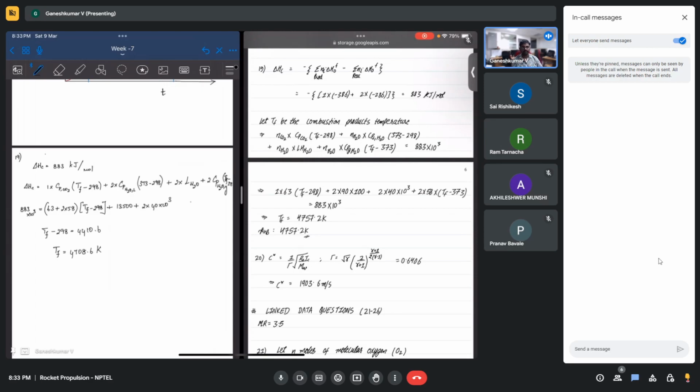So basically, what I feel is that a 25 Kelvin difference in the heating of products should not lead to a 700 Kelvin difference in the adiabatic flame temperature. So in that way also we can think about it. So this also makes sense. A 25 Kelvin difference, since it's 2 moles, leads to approximately a 50 Kelvin difference. Your product is not the same.